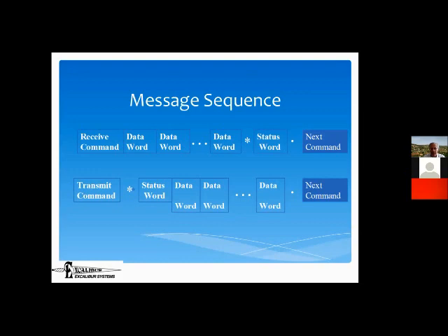So following this receive command, I expect to see 7 data words, right? And these 3 dots here just indicate some random number. And in our case, altogether, there are going to be 7 words. So these 3 dots are going to be 4 words, and the 1, 2, 4, and 1 is 7. And they're going to be contiguous, right? So on the bus, there's no space between the words. You can see where one word starts and another ends. And we'll get to that when we discuss physically what the bits look like. But right, in terms of the command, you have the command word, contiguous to the command word, 7 data words.